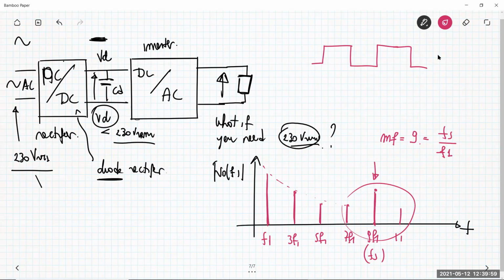But basically, it is a little bit too difficult to isolate F1, because the first harmonic you have to filter out is the third harmonic, okay? And so my filter action should be very steep in the interval between F1 and 3F1. So basically this happens in the Doppler modulation.